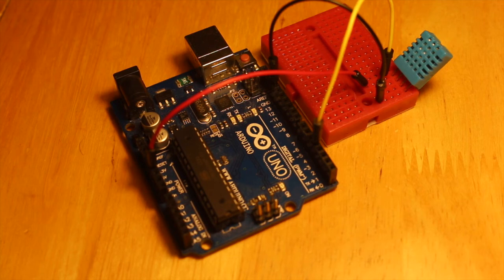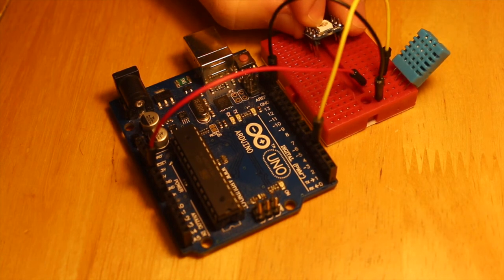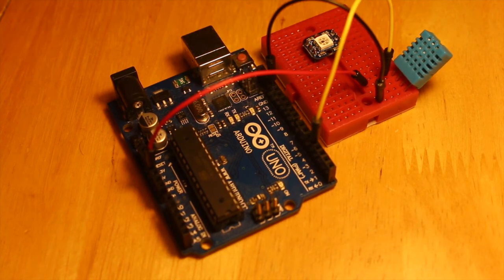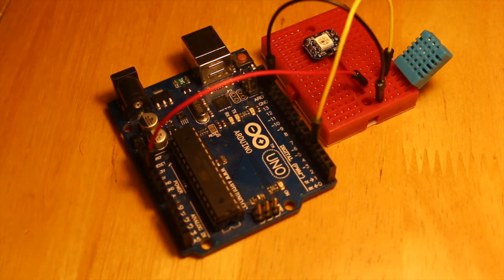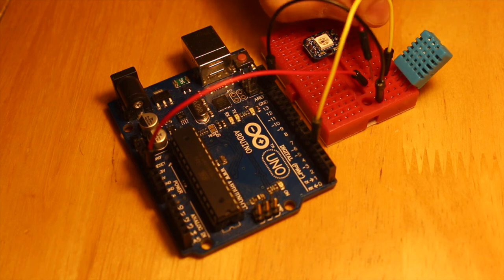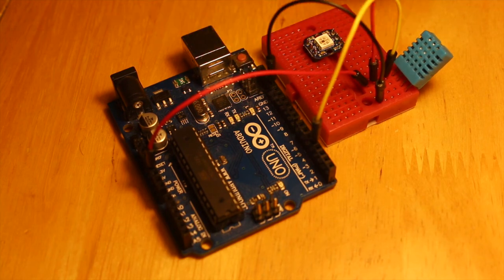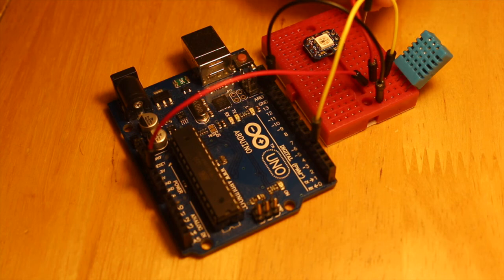Perfect. This way we have our temperature sensor connected. Now it's time for the LED. I'm just going to connect to the board here. Because the Arduino only has one 5 volts on this side, I'm going to plug into the same position as the 5 volts on the temperature sensor. So I'm just connecting here. And I'm going to put this cable on the plus from the LED.